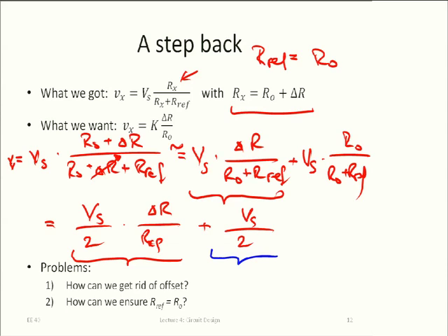So yes, actually there was a good question. Our choice, we want to make our RF equal to our R0. How are we going to make two components identical in value? Well, the answer is very, very simple, but it's also as important as it is simple. Of course, we use the same value, right? But the way we do that is we actually physically use the same component.